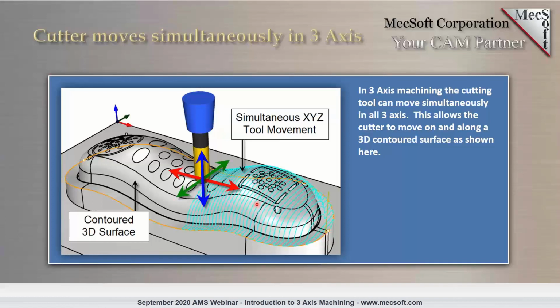Now, the next thing we will be talking about is, for 3-axis machining, how we would be orienting the part and how we will go through the setup process to be able to program these parts using 3-axis machining. To demonstrate this, I will switch over to our CAM product. I'm going to be primarily demoing the RhinoCam solution today.